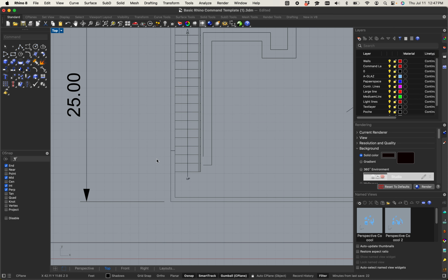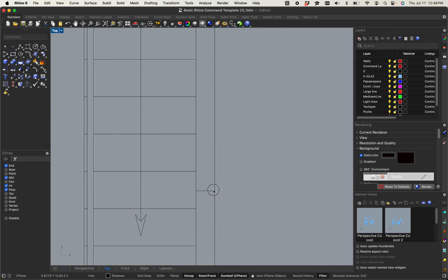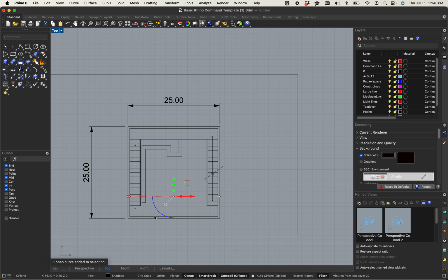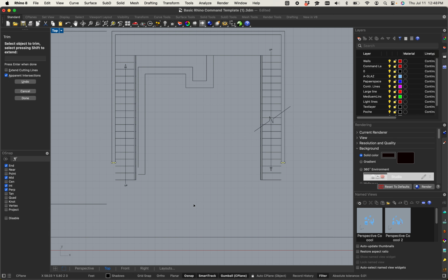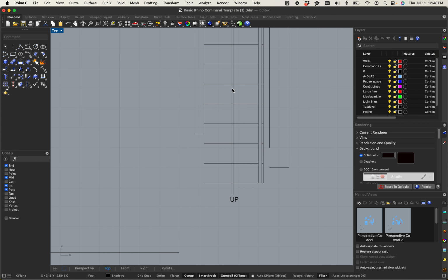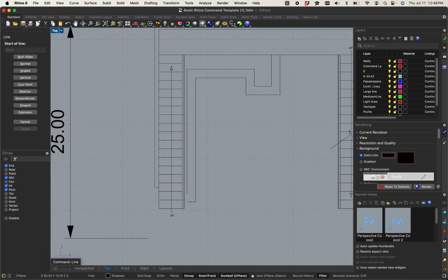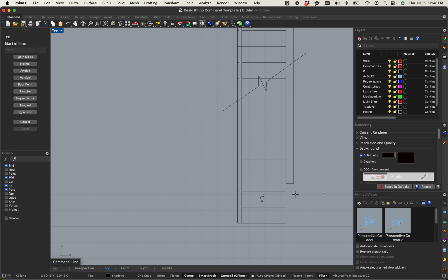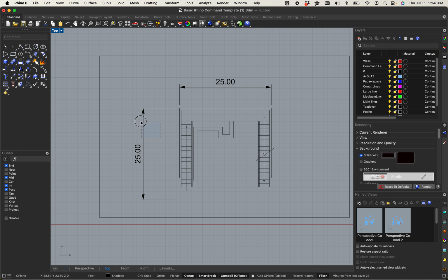But yeah, maybe I don't want this exterior wall here, so I'm going to take that piece. I'm going to hold shift and get that piece as well. That way when I hit trim, enter, I can just in one fell swoop get rid of something, right? Uh-oh, some of my stairs need the rest of those, so I'll just draw a line. Not really a big deal. Again, it is completely two-dimensional, so still in that second dimension. Let's go ahead and hatch it, and let's get rid of those, kind of in the way.